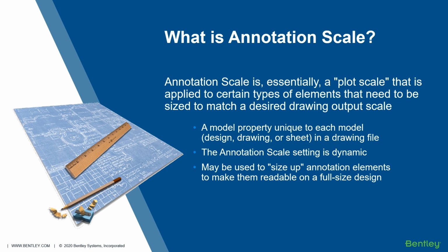So we'll begin by asking, what really is annotation scale? Essentially, annotation scale is a dynamic scale factor that can be applied to particular element types for the purpose of accommodating the proper display of those elements at various print scales. So you can think of it as a print scale that, as desired, may be applied to various types of elements that are placed in your designs to help size or resize them relative to the desired print scale of